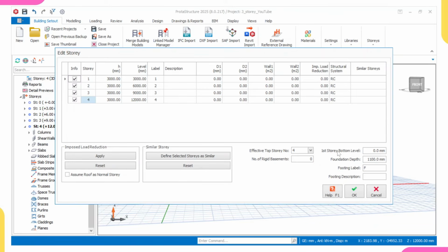Coming over to this point, what will be our foundation depth? Since we are going with beam raft foundation, we'll be using the foundation depth of 100, so 1 meter. Then if it fails, we will not increase it, because we are going for beam raft foundation.